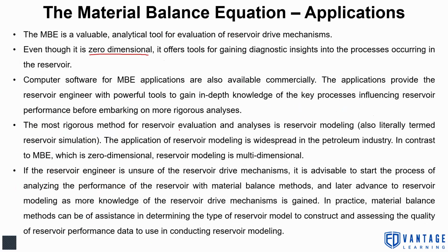The most rigorous method for reservoir evaluation and analysis is reservoir modeling, in conjunction with material balance analysis. If the reservoir engineer is unsure of the reservoir drive mechanisms, it is advisable to start analyzing the performance of the reservoir with material balance methods, and later move to advanced reservoir modeling as more knowledge of the reservoir drive mechanisms is gained. In practice, material balance can assist in determining the type of reservoir model to construct and in assessing the quality of reservoir performance data to use in reservoir modeling.